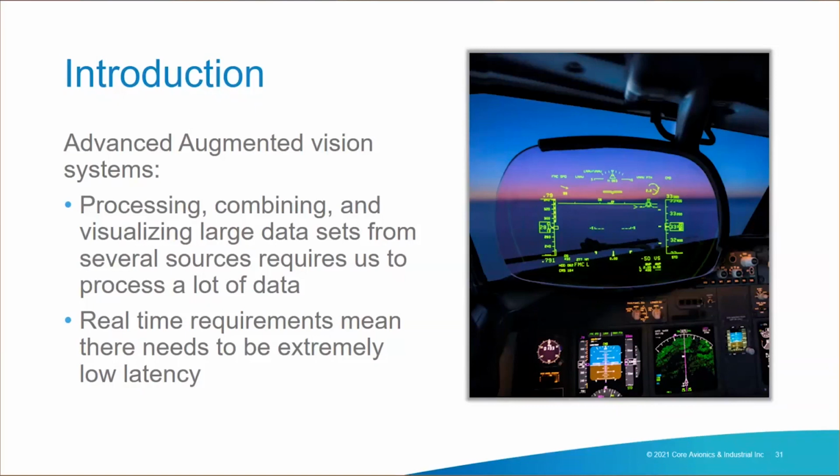And when we need to do this in real time, for example, if you have a display, you might be updating it somewhere between 30 hertz and 60 hertz, or if you even have a heads-up display, the refresh rate becomes more and more important. You could be updating at a rate faster than that. If you're using, for example, a radar or LiDAR sensor that's gathering a point cloud of data, per sample you're looking at hundreds of megabytes to even gigabytes of data. And if you need to update that at 60 hertz, for example, you're looking at 30 gigabytes per second or even 60 gigabytes per second of data that you now need to process in order to display something in real time.